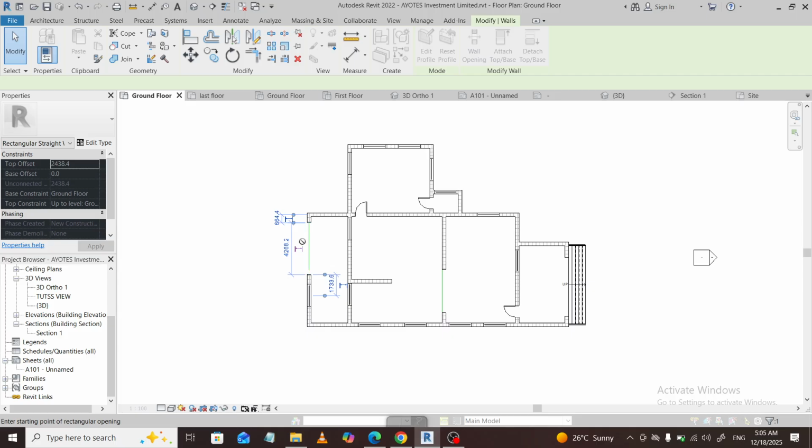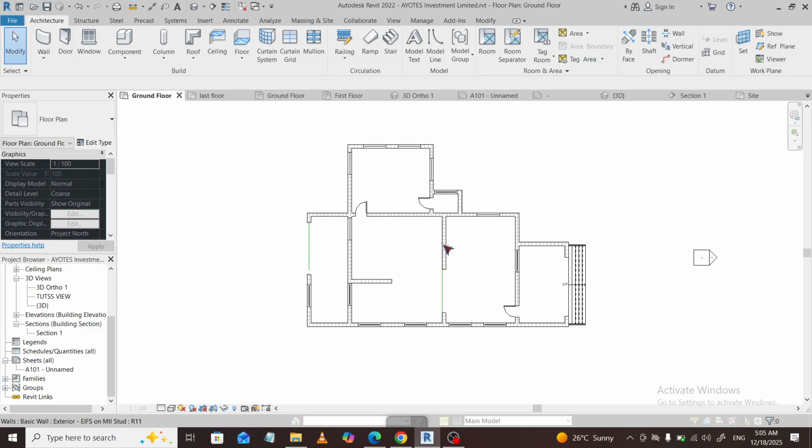Once the wall is selected, you'll enter sketch mode, choose the rectangle sketch tool, then click to set the first corner of your opening and click again for the opposite corner. Use the temporary dimensions that appear to dial in exact width and height. Just click the blue dimension text and type a value. Snaps will help you align to levels, grids, or nearby geometry.